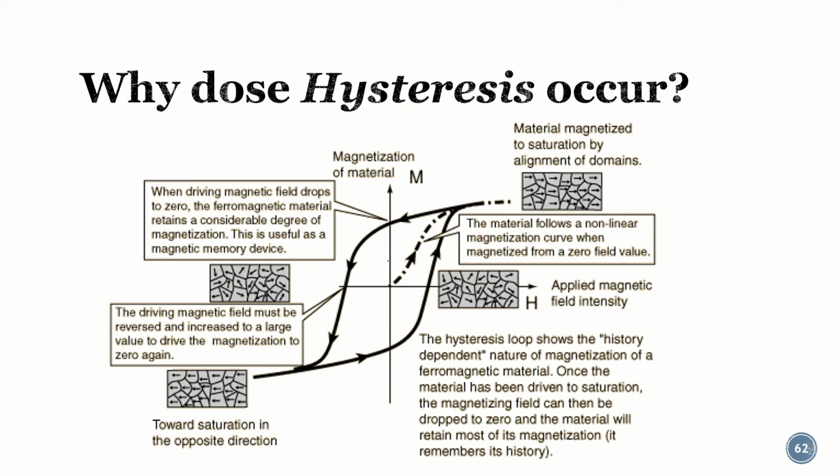Basically what is happening is that when we apply some magnetomotive force, eventually we get the maximum flux due to the alignment. And if we remove that, we still have some internal flux, which is basically the loss. We want to make the total disalignment, but some of the domains are not totally disaligned. So there is some residual flux here where the applied force is 0, and that residual flux is basically the loss.